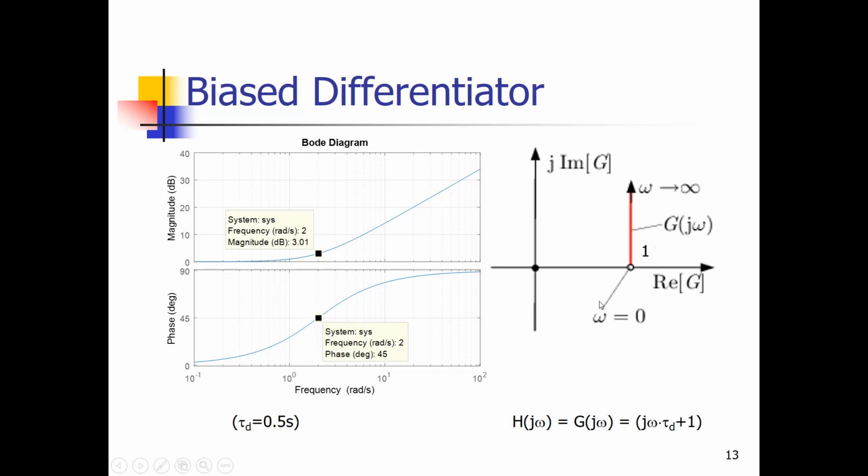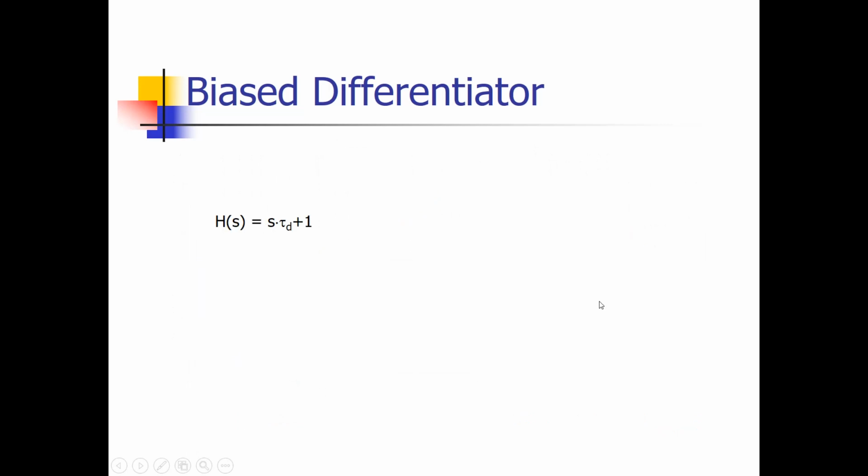Remember that. Okay, last but not least, we're going to look into the pole zero plot. We've seen that the transfer function in the s domain is H(s) equals s times tau d plus 1. So we can say, well, that is s times tau d plus 1 divided by 1. So in the numerator, there is an expression with s, which yields a zero.